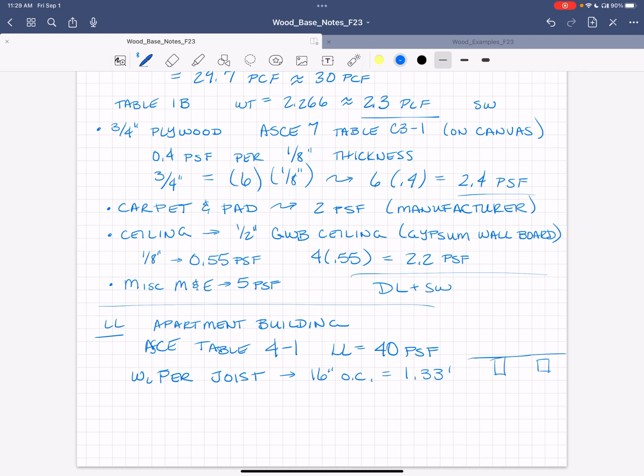So if I am looking at a joist member or beam member, it's from this one to the next one, right? So I go from here to here, halfway. He gets to carry all that load. So he's going to carry all that load from the flooring system, as well as his self weight, as well as the live load that's on that piece of flooring system.